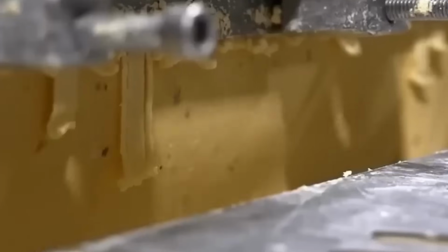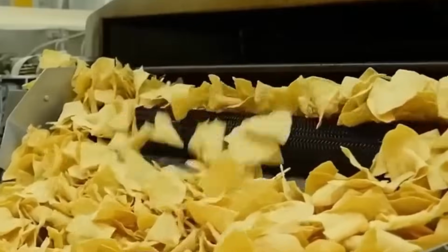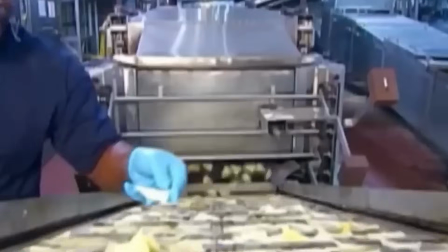The cleaned corn is fed into a steeping tank or continuous cooker where it is exposed to water at temperatures between 80 and 100 °C. The corn remains in this system for 30 to 45 minutes, depending on its initial hardness and desired hydration level. Water is continuously circulated and filtered to remove loosened pericarp, and the corn's internal moisture content rises to around 40 to 45%. Cooked corn is discharged onto dewatering screens and conveyed to the stone mill.